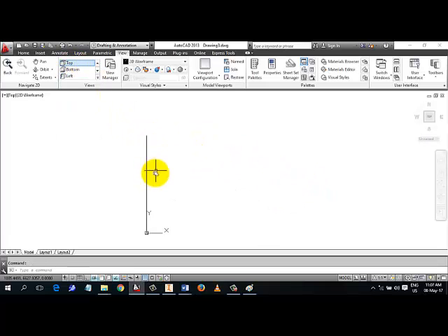So that is it. But there is a problem. I don't like this thing following my drawing around. This XY. So you simply type UCS icon. When you type UCS icon, User Coordinate System icon, that's the name of the icon.